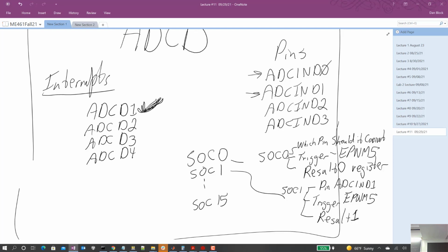That's just the life of that timer. Yes, it can generate an output signal, but it also can just be a timer. And so for that reason, this ADC unit allows you to trigger the timing of the ADC conversion with the PWMs, because they are, for the most part, timers.